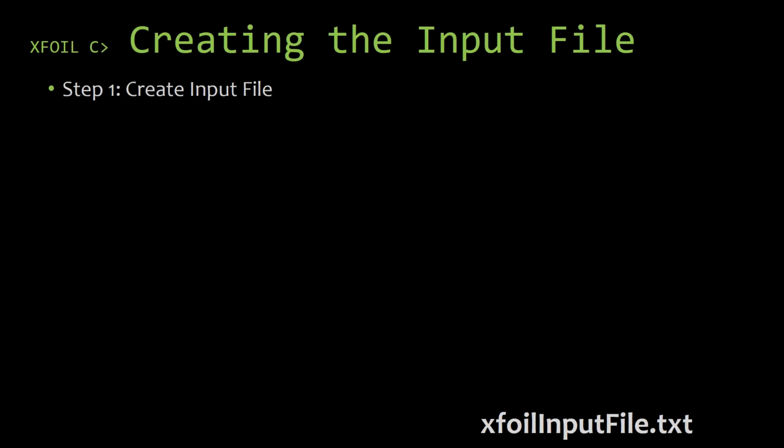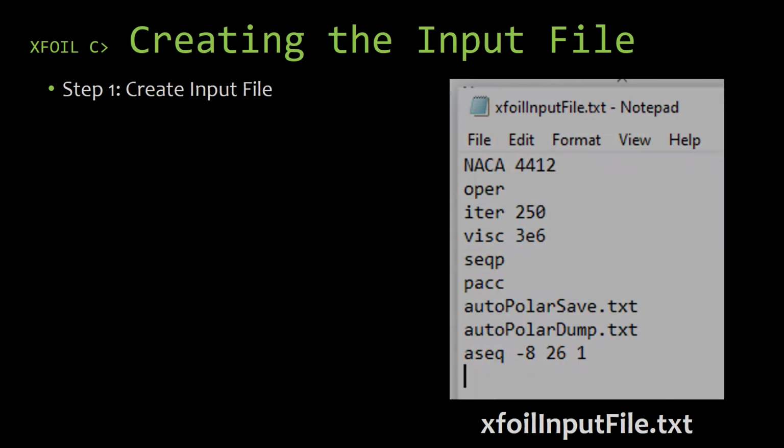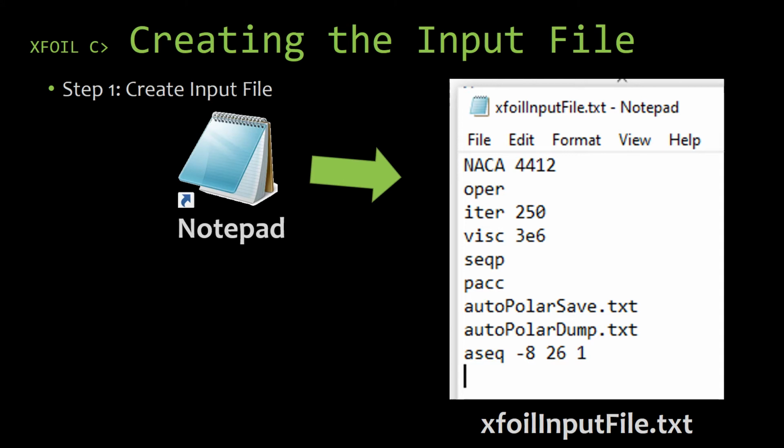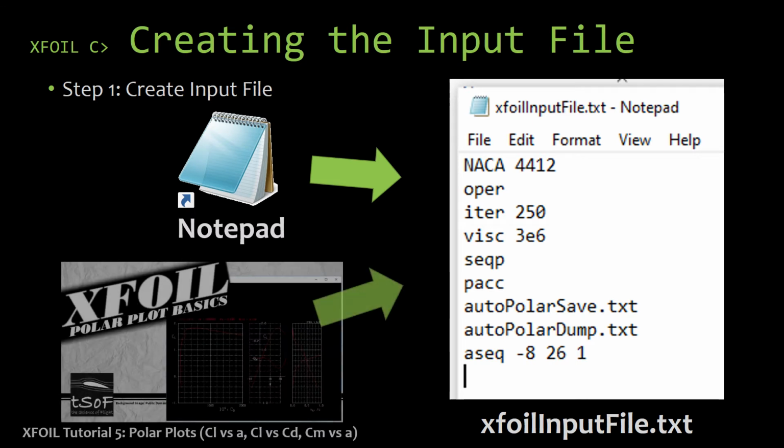The first step of running Xfoil using an input file is, of course, creating the input file. I'm going to go ahead and use the Notepad application. So find your Notepad and double click it open. Now for the list of commands on what we want Xfoil to do, I'm going to go ahead and try and replicate what we did in the Polar Plot Basics video.